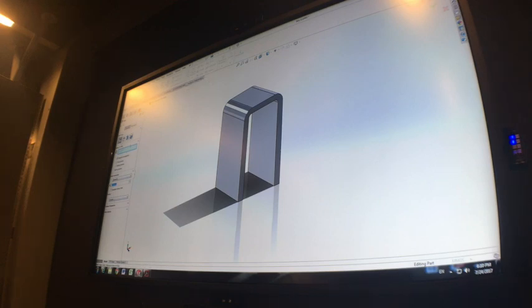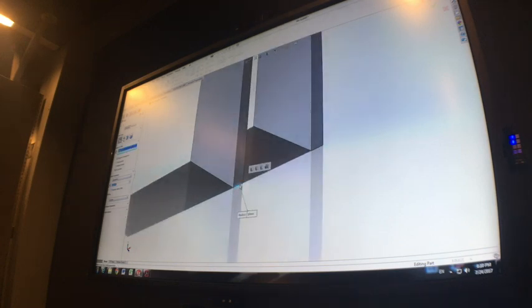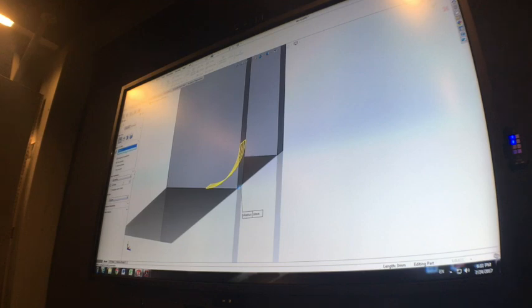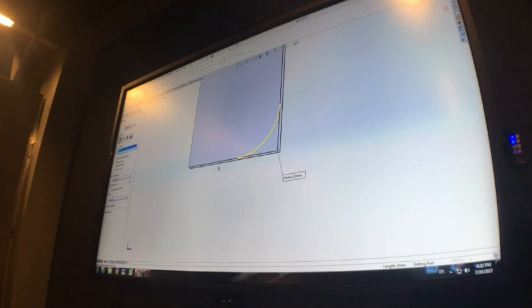So how the fillet tool works, you can see there's 4 different fillet types. Typically, you only use the first type, but when you get a bit more advanced, you can experiment. You select an edge, it's going to fillet that edge. To see that, turn on full preview on the left. You can see the yellow preview where it's going to cut away that edge. This is the 10 millimeter radius, which means 10 millimeters to the left and 10 millimeters up, and then it creates an arc in between, and that arc's going to be tangent to those 2 lines.